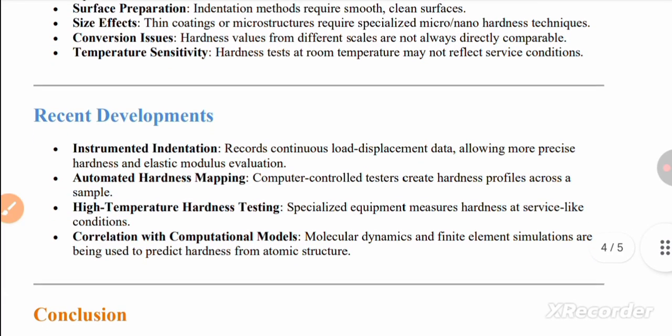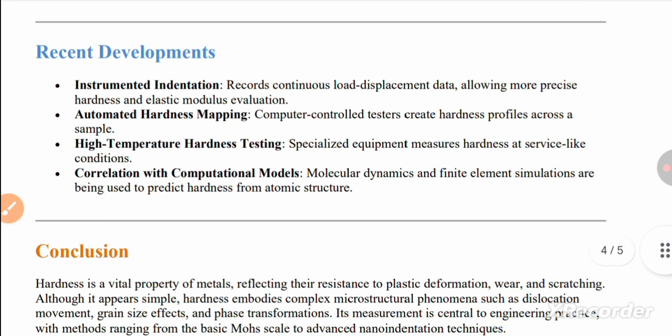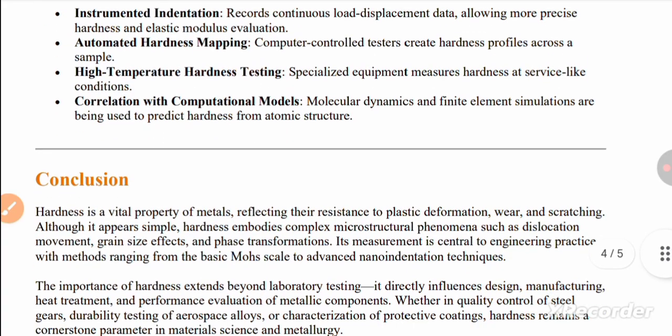Recent developments. Instrumented indentation records continuous load displacement data, allowing more precise hardness and elastic modulus evaluation. Automated hardness mapping, computer controlled testers create hardness profiles across a sample. High temperature hardness testing, specialized equipment, hardness at service-like conditions. Correlation with computational models, molecular dynamics, and finite element simulation are being used to predict hardness from atomic structure.